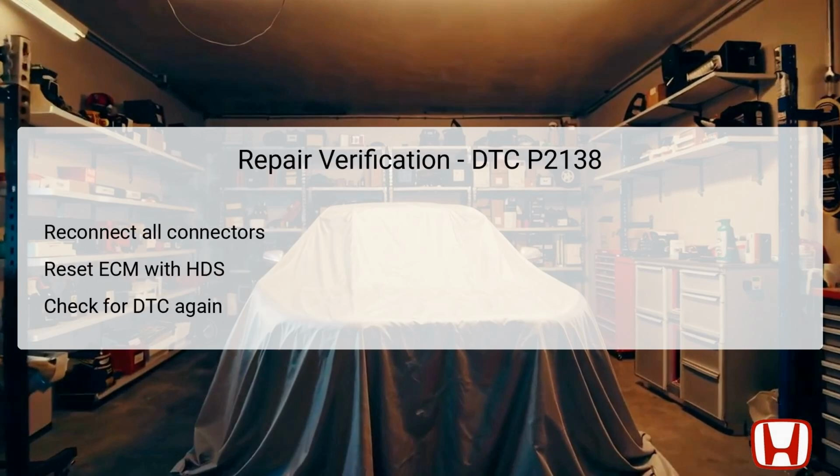The final step consists of repair verification to ensure all issues tied to DTC P2138 have been properly addressed. Begin by turning the ignition switch to the lock position and carefully reconnect all previously disconnected connectors, ensuring secure connections to avoid future issues. Then, using the HDS, reset the ECM, allowing the system to clear any leftover fault codes and adjust its parameters based on the repairs made.